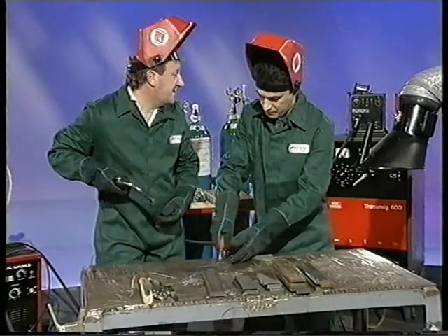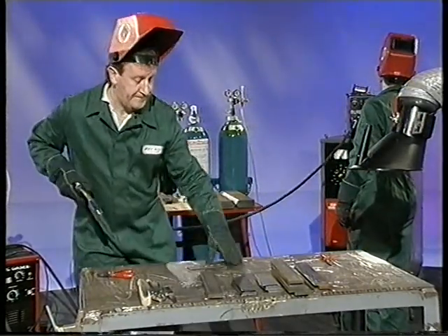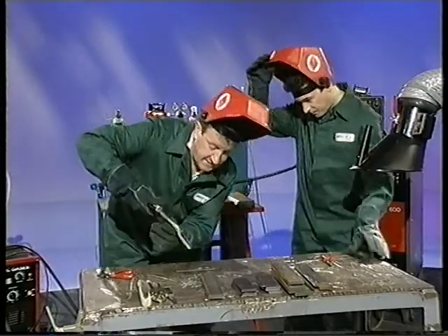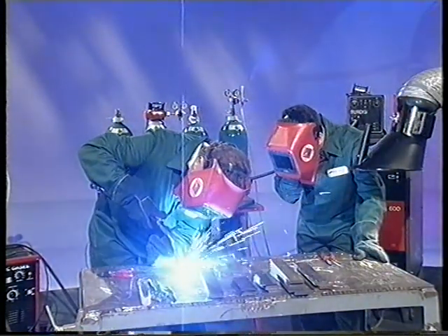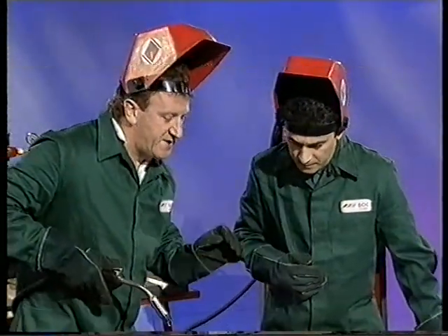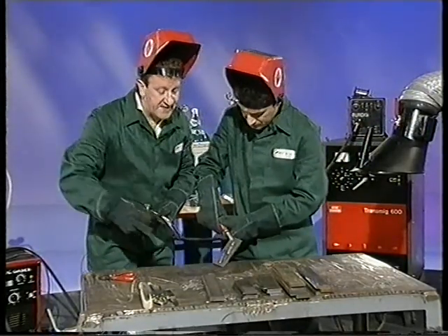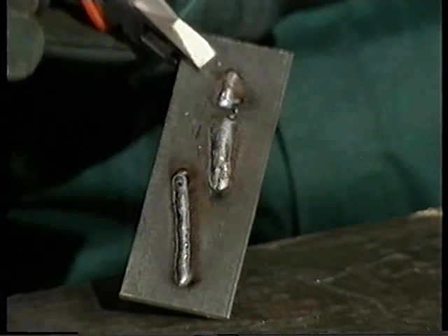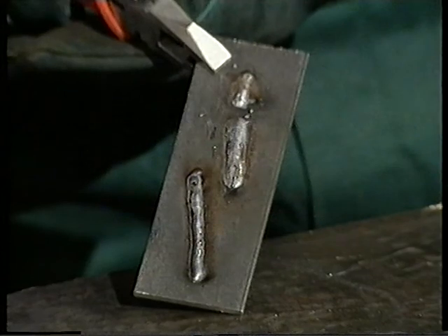Okay. So if you would please turn that back to about 6 meters a minute, and let's see what we have there. Okay, mind your eyes. Once again, spatter. Not so much smoke, but nonetheless, the sound of that weld was much better. Yeah, it really was short-circuiting quite nicely. And yes, please use that because it is hot. The weld bead itself is now reasonably well spread out, and there wasn't that much spatter being produced. Right. That, I would suggest, is a good balanced dip welding condition.